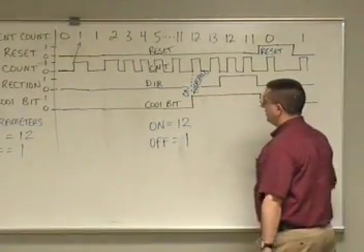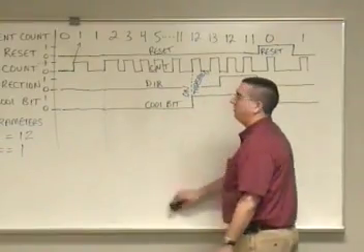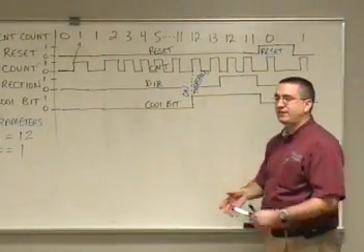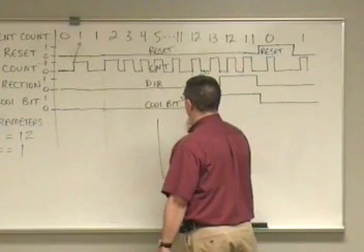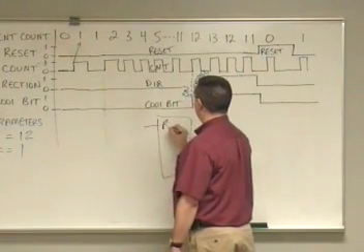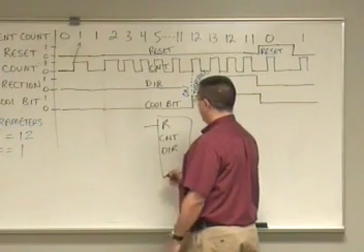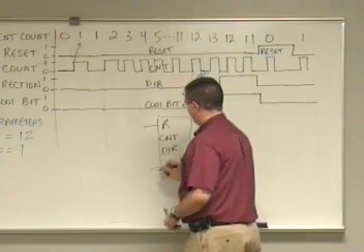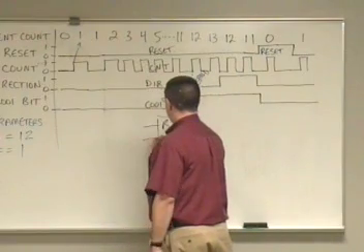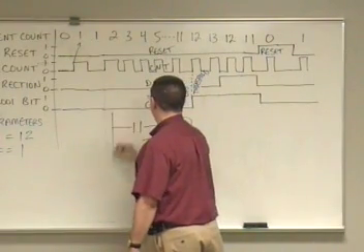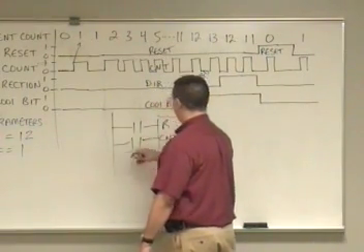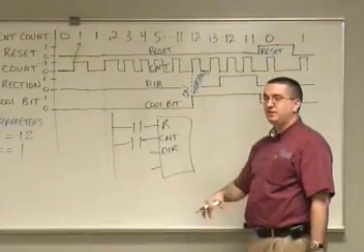Maybe you just want to count up to 12, turn something on, and then have that reset it. You have the reset, the count, the direction, and then your parameter pin. You might only use 2 of the pins, and on the LOGO, that's okay to just leave the other pins empty.